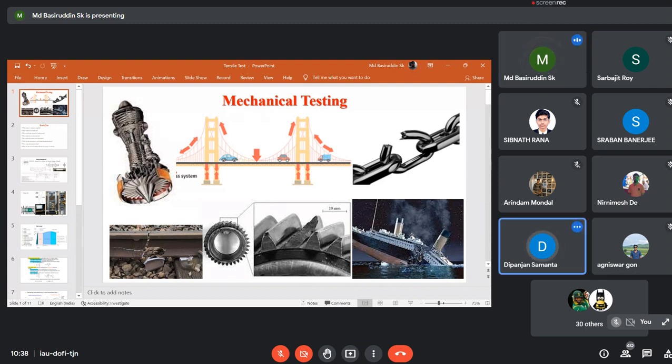As you have said, the rivet pop-up may happen due to electrochemical reactions of the materials coming into contact with the environment, such as a moisture environment or other adverse environmental conditions, as well as when impact loadings act on that particular ship, which enhances the deterioration of the rivet joint. So that may be one reason for the rivet failure.